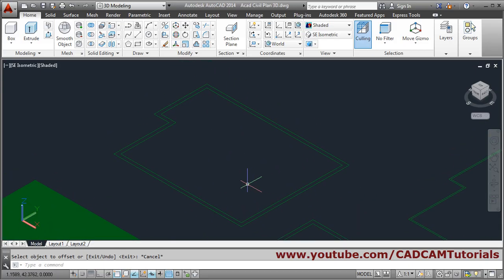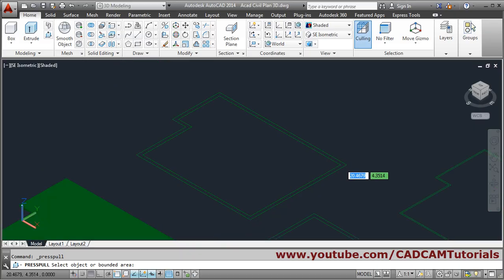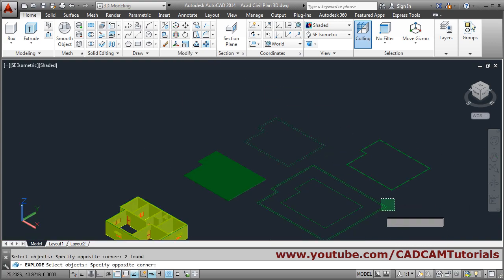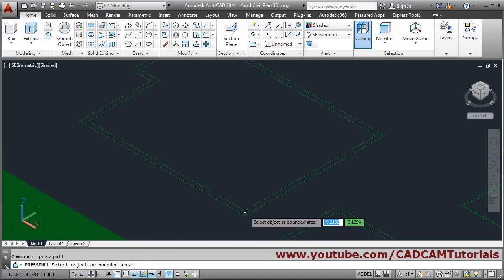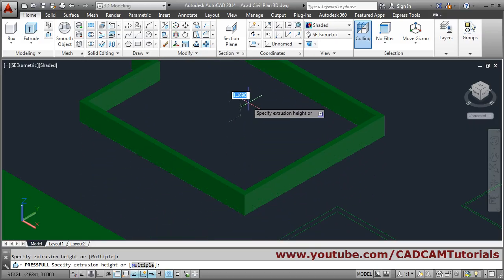Then for the parapet wall, again use press pull. Now it is again not getting press pulled, so we will just try to explode it. Sometimes a polyline doesn't get extruded, so we will explode it. Click on modify, explode, select the object, then enter. Then again try to press pull it. Okay, now you have to catch that point. Now it got highlighted, that means it can be press pulled. Click there and give the height of 0.75.